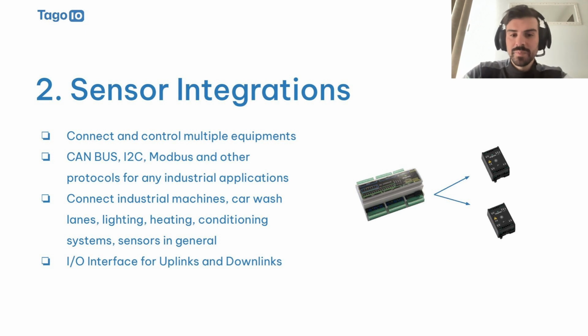And then finally, you need a device that can send and receive data from the protocol network to any other device or system. For example, you could use a CAN bus shield to connect an Arduino board to a CAN bus network. You can also use an RS485 module to connect a Raspberry Pi to an RS485 network, and also use an I2C adapter to connect a PC to the I2C network. So this is all the theory. Like I said, later on we're going to see some examples of this integration.